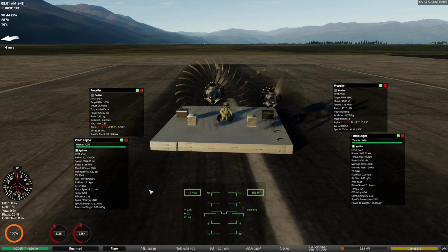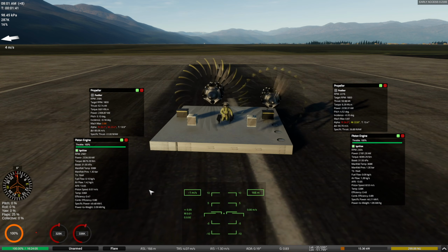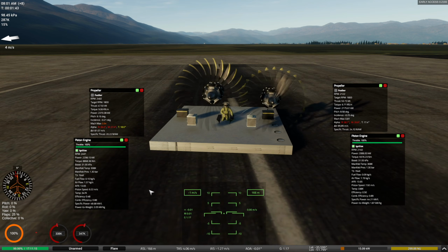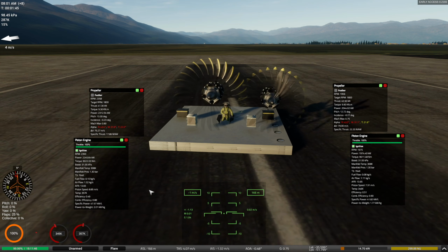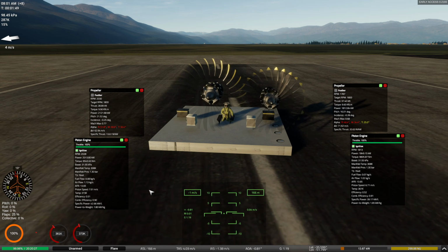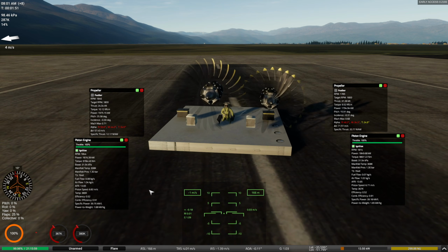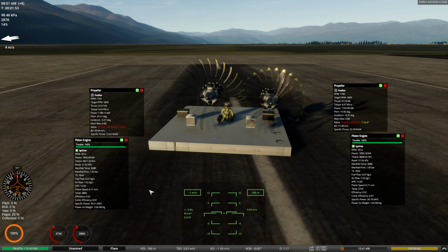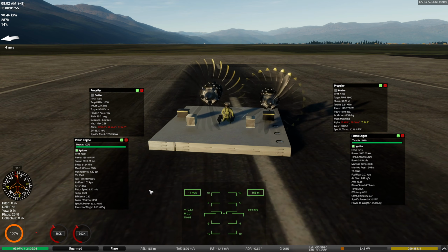The third blade is the scimitar blade. It is more efficient than the control group, but has an additional property that makes it useful at higher speeds and altitudes. Because the blade is swept, it is more efficient at higher tip Mach numbers in the same way that a regular swept wing is. I'll get into this property more in the wings tutorial.